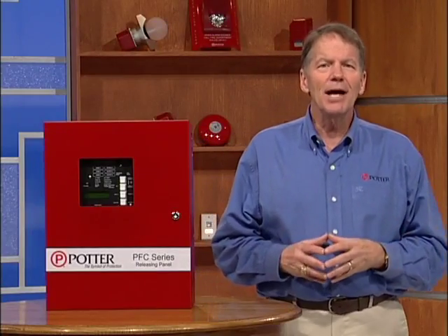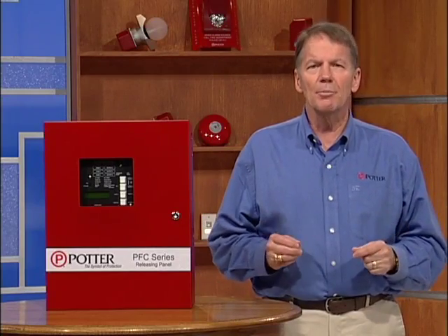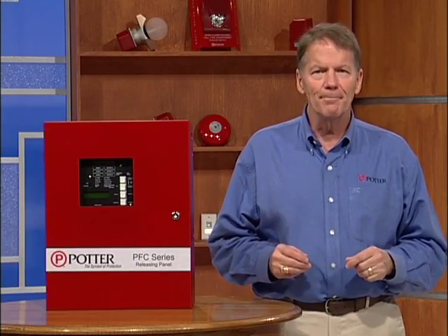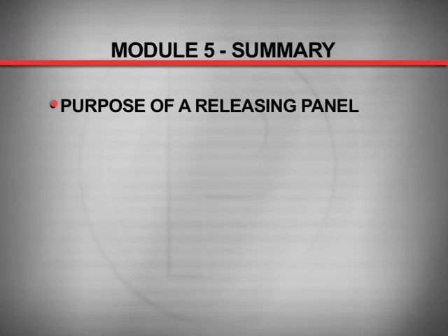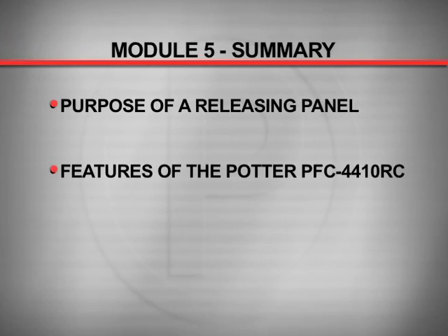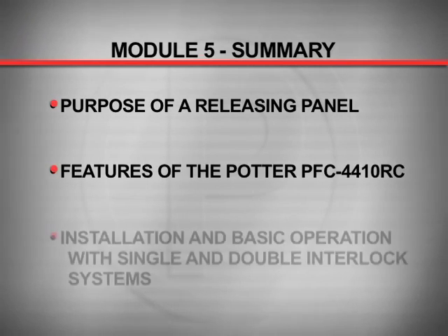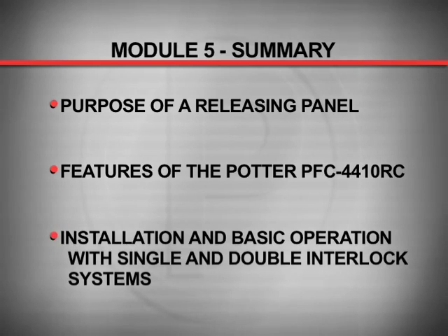This concludes Module 5 of the Potter Sprinkler Monitoring Product Training Program. In this module, we reviewed the purpose of a releasing panel, the features of the Potter PFC 4410RC releasing panel, and the installation and basic operation of releasing panels with single and double interlock systems.